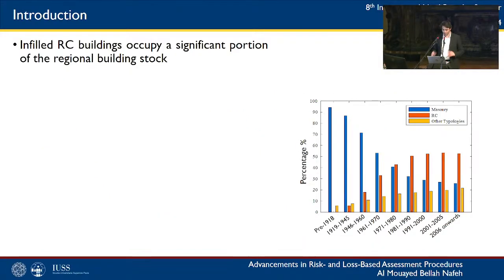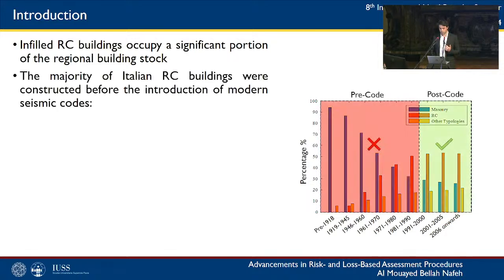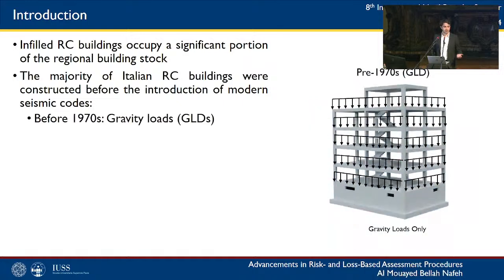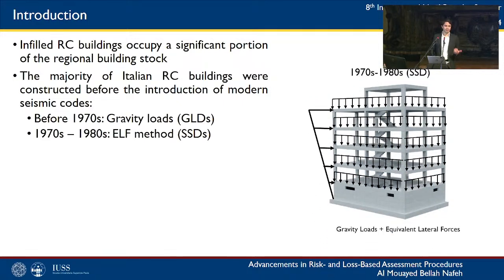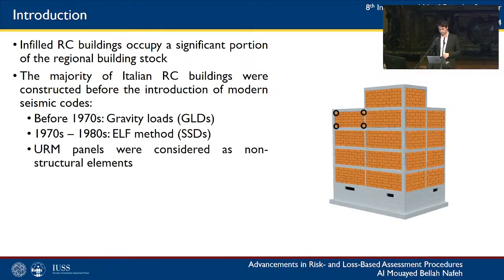So without any further ado, what seems to be the issue here and how can we address it? Well, if we were to inspect our regional building stock, we would discover that infilled RC buildings occupy a significant portion of the existing built environment, and that the majority of said buildings were designed before the introduction of modern seismic provisions. For example, buildings constructed before the 1970s were designed to resist gravity loads only, and it wasn't until the beginning of the 1970s that we started witnessing the implementation of the equivalent lateral force method as a substandard means to quantify the seismic action a building is expected to resist.